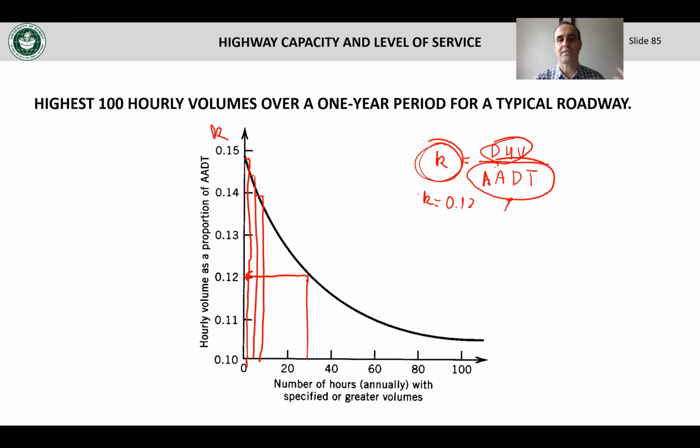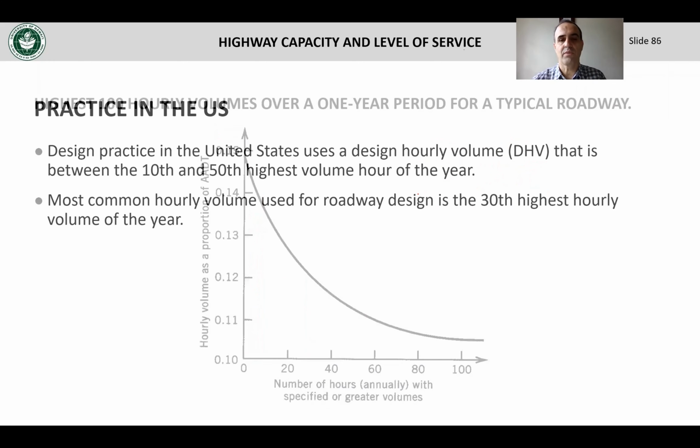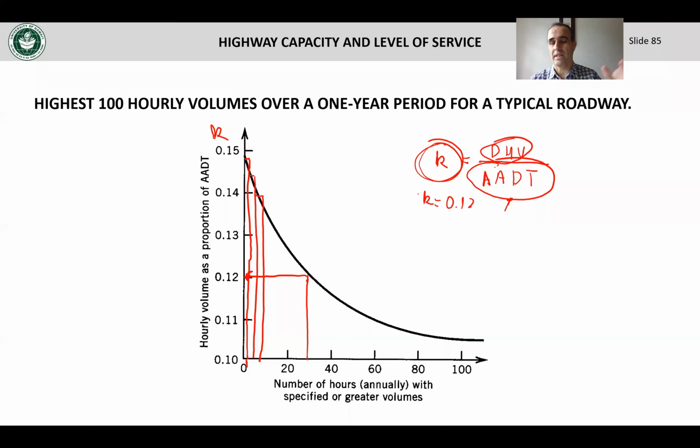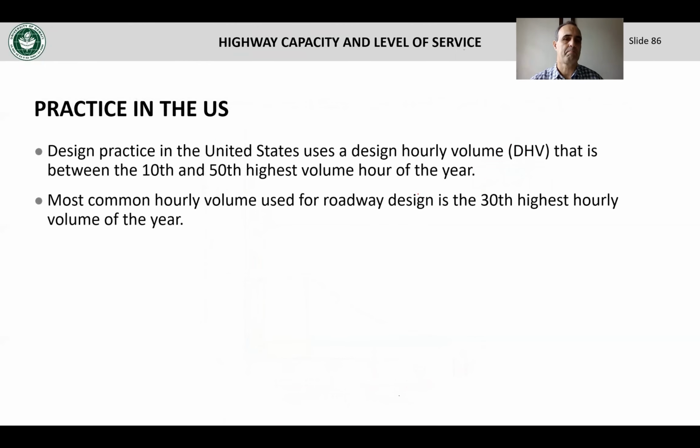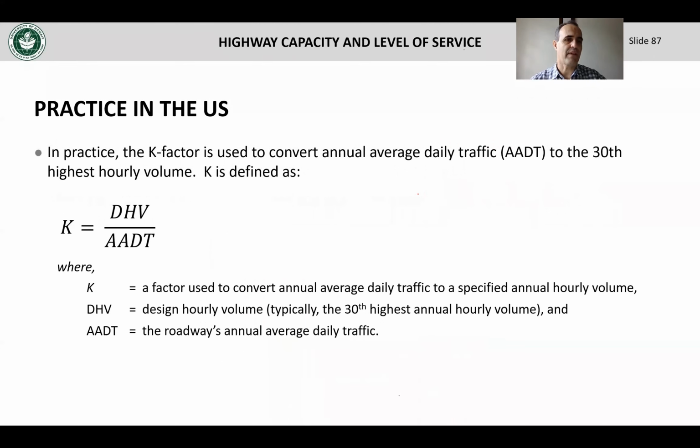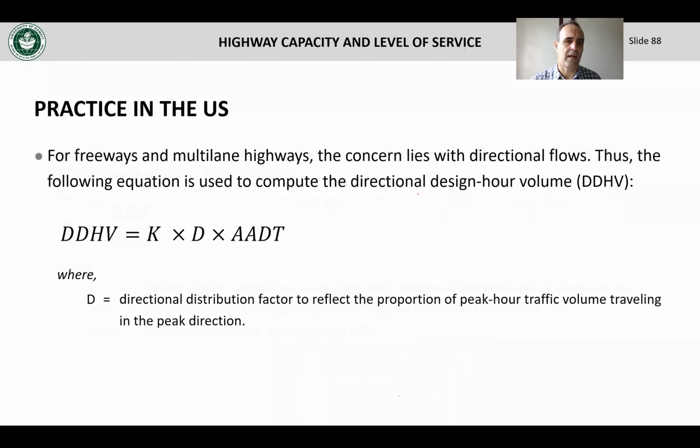Okay, so I'm just trying to tell you how that value of 3,000 that we told you in that problem comes about. So you have that equation there in the notes, and in the next note it's basically the same, but also most of the time the AADT will be given in both directions. In that case, you have to multiply by the directional factor. But that's it. With that, you will get the design hour volume for design.